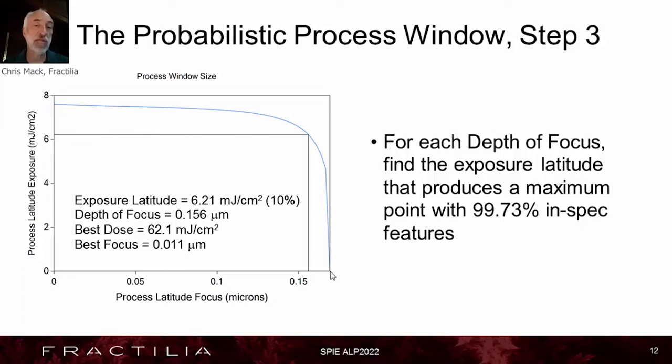Here I set the exposure latitude to be 10% of the nominal exposure. We get a best dose, a best focus, and a depth of focus, all determined in this rigorous probabilistic way.